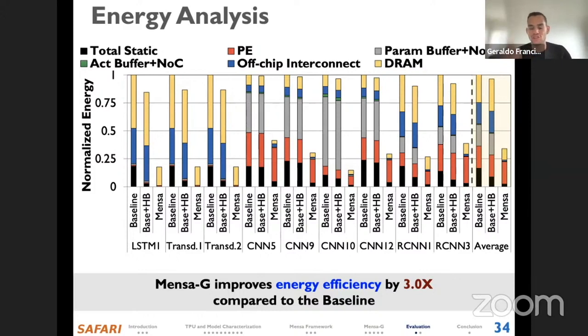So then you don't fetch so much from DRAM. There is a particular technique that we use, to reuse the data that is placed in the registers of the processing element array. So we try to reuse that value as much as possible, and based on that, we don't need to fetch so much from DRAM. So there is also that point.